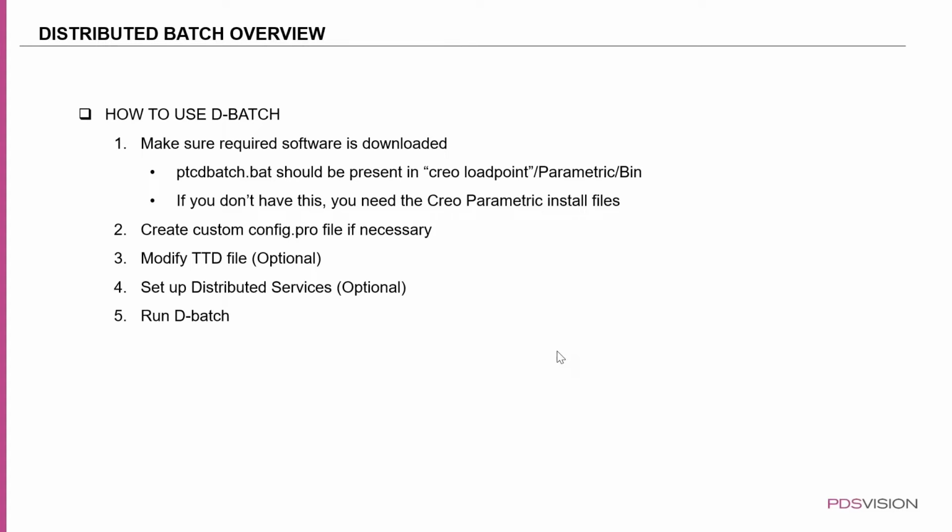So I do just want to address 2 questions that I got that I think are relevant. So first question, can you run a batch process overnight? The answer is definitely yes. So if this is going to take a long time, you can just let it go and let your computer run. The only caveat there is you're not going to be able to use Creo during that time. So doing it overnight is probably a good idea, because as this is running, using Creo is going to kind of mess this up.